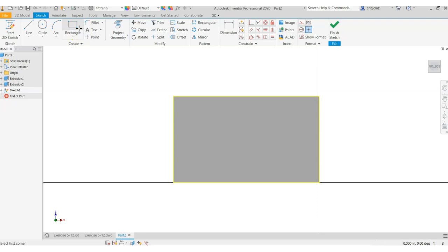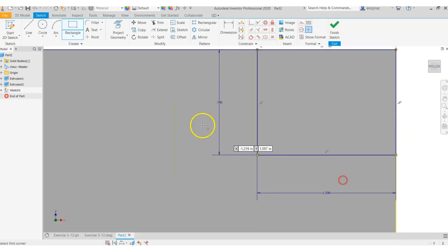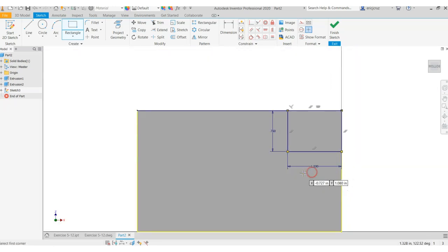We're going to do the first cutout. We're going to do the cutouts, the extrude cutouts in one sketch. We're going to do each cutout one at a time. So the top right corner should snap to it, and your dimension on that left side, the highlighted one that's in blue right here, that is going to be 0.76 tab, and that's going to be 1. Let me zoom in. So 0.76 and 1.